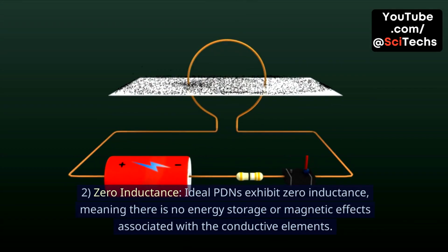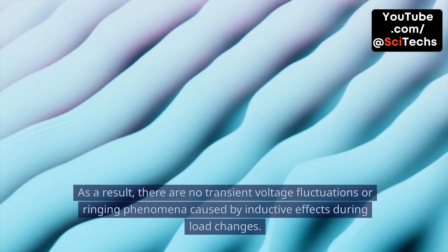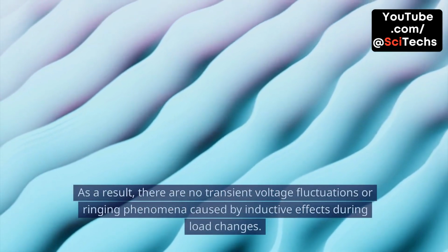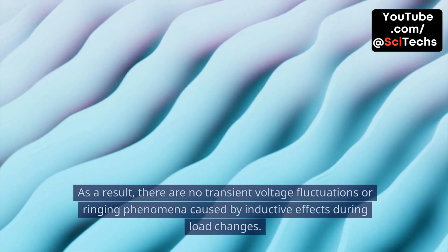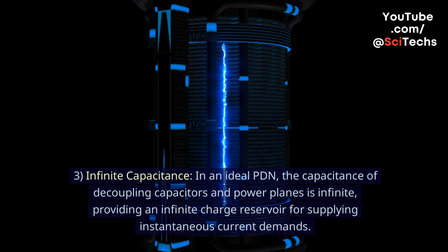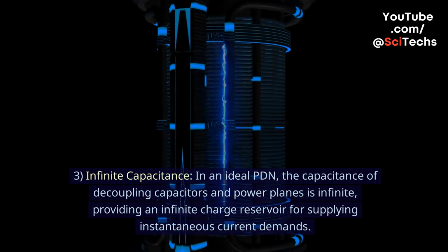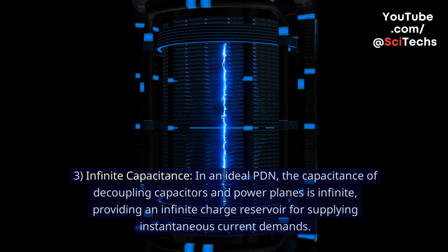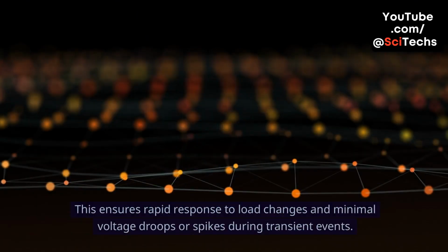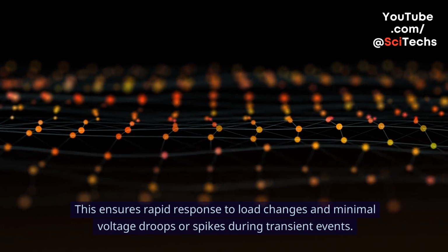2. Zero inductance. Ideal PDNs exhibit zero inductance, meaning there is no energy storage or magnetic effects associated with the conductive elements. As a result, there are no transient voltage fluctuations or ringing phenomena caused by inductive effects during load changes. 3. Infinite capacitance. In an ideal PDN, the capacitance of decoupling capacitors and power planes is infinite, providing an infinite charge reservoir for supplying instantaneous current demands. This ensures rapid response to load changes and minimal voltage droops or spikes during transient events.